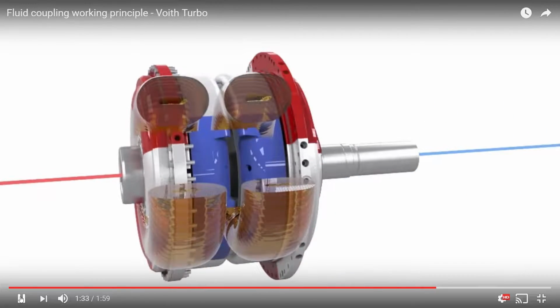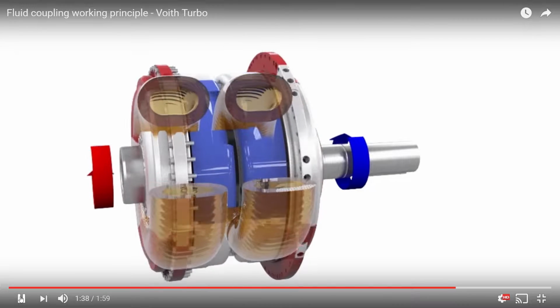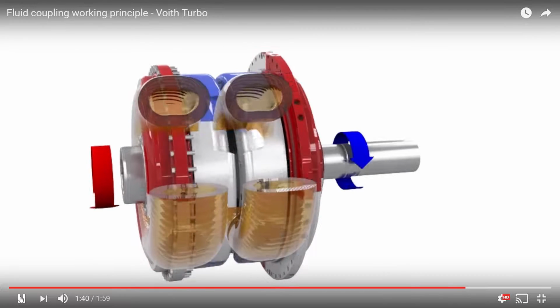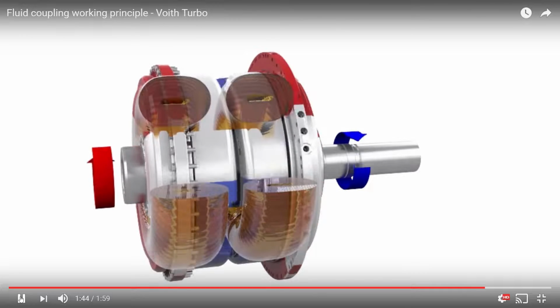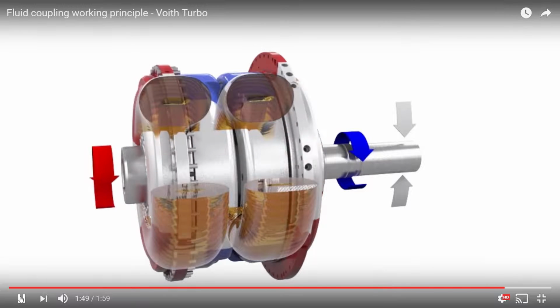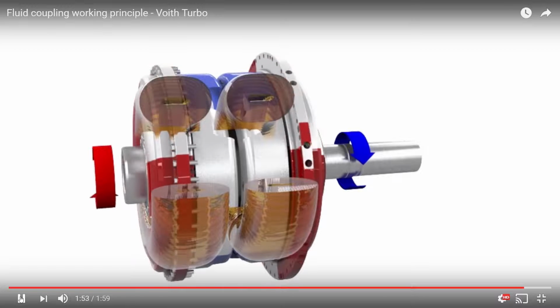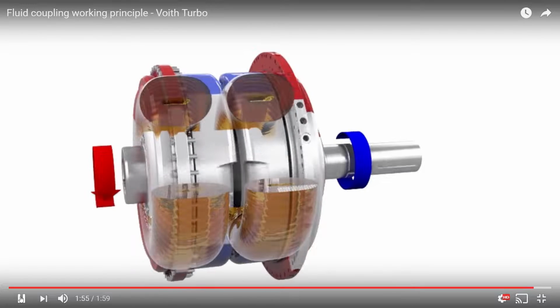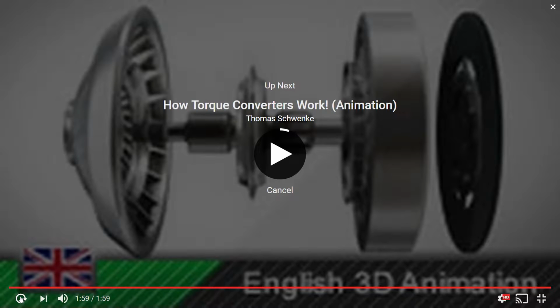Now that squiggly line is showing you how it can smooth out vibrations. So when your torque converter is not in lockup, it's going to actually smooth out some engine vibrations, some road vibrations, which is another reason why when you're in TCC lockup, torque converter clutch lockup, that's typically when we experience engine misfires, or when we can actually feel the engine misfires.